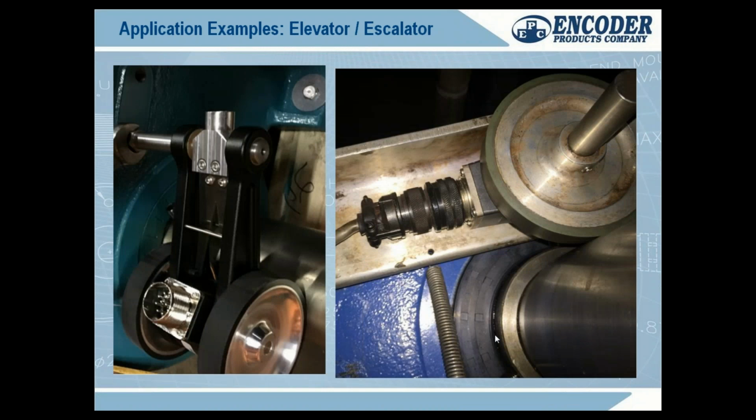This is another example of a wheeled encoder, and this is one you probably haven't thought of, but it's been very successful. Large bore. This is an escalator I worked on in Washington, D.C. Most escalators are using a setup like this, a very nice encoder, not ours. But they were taking a screen door spring from Lowe's or Home Depot. They'd taken a piece of angled aluminum and self-tapped through the housing of the encoder to hold a wheel against the shaft. Why were they doing that?